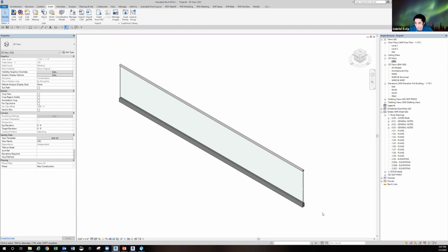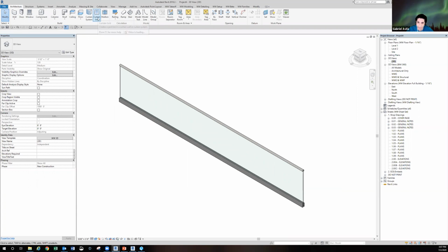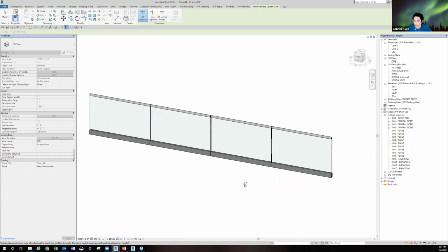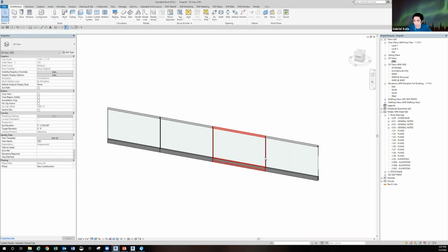All right. So because we created this as a curtain wall, it's kind of easy, kind of like how we're making our curtain walls in operations and in sales. You can just add curtain grids to break them up. So say you had some joints in here, 5 feet. You can go every 5 feet or whatever spacing you want, and there's your joint. So pretty easy to do. Use your curtain wall feature or curtain grid. If you don't want a joint, you can come in here, tab to get the curtain grid, and just delete it, and it goes away. Pretty easy to manipulate.